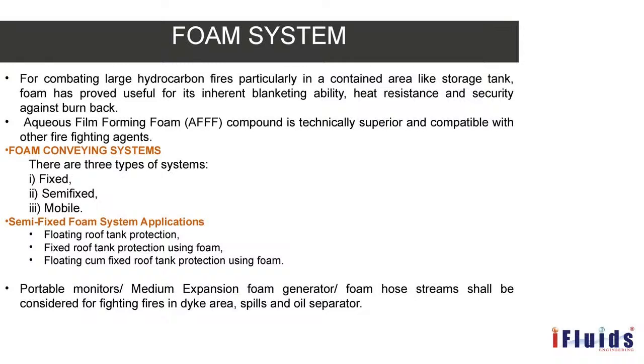So the semi-fixed foam system is applicable. Then the major point mentioned here is that it depends upon the tank diameter. The minimum number of foam discharge outlets is also mentioned here.